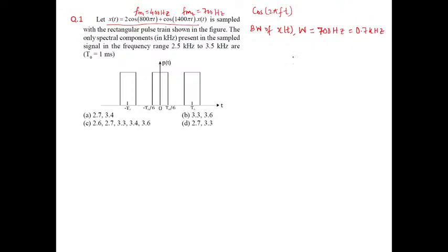Rather, we should write it like this: the frequencies present in X(f) are 0.4 kilohertz and 0.7 kilohertz. The only spectral components present in the sampled signal in the frequency range 2.5 kilohertz to 3.5 kilohertz are...